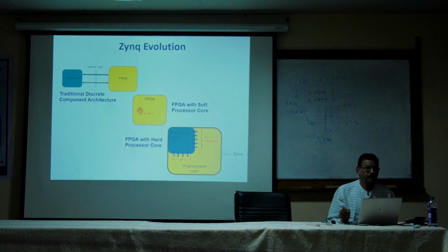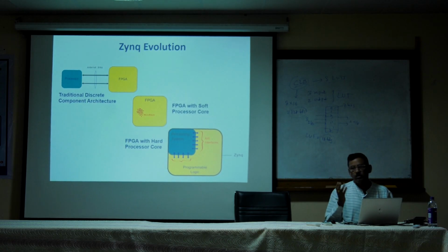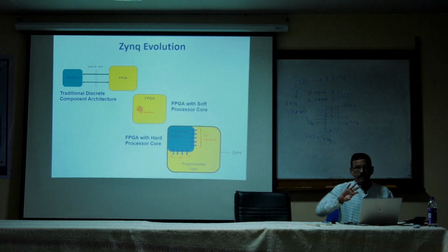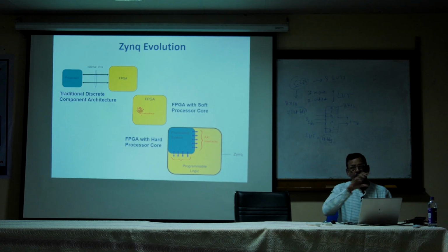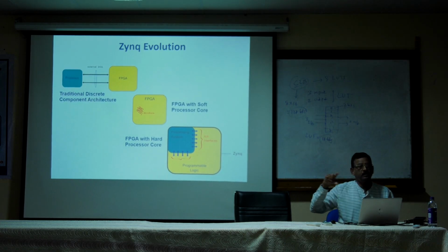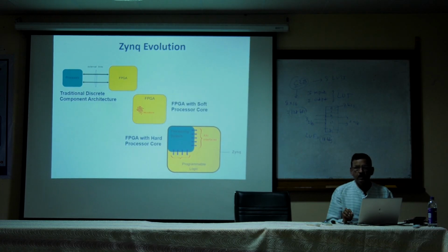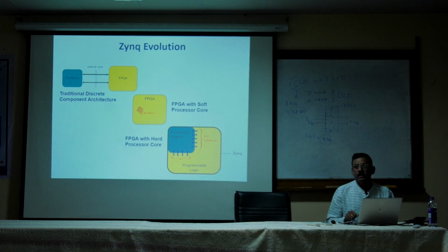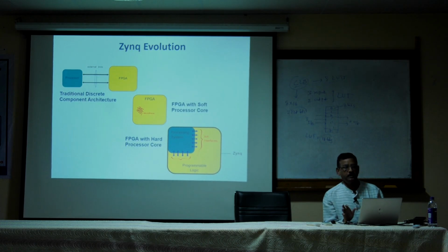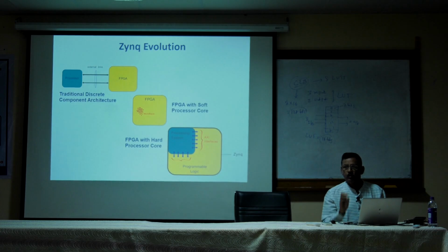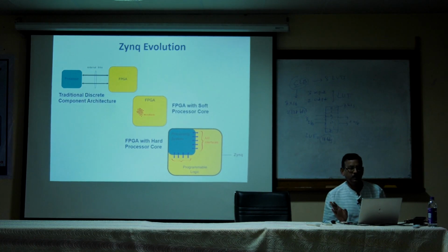Processing core, in addition to whatever we discussed in the morning: interconnect resources, connections, vertical and horizontal tracks, lanes, as well as switch matrices, and also dedicated memory and dedicated computing blocks, DSP blocks, plus CLBs, and plus one more is processing engines, processor cores are also present. In Virtex 4 FPGA there are 4 processing cores inside. Okay. PowerPC processing core engines are present inside.